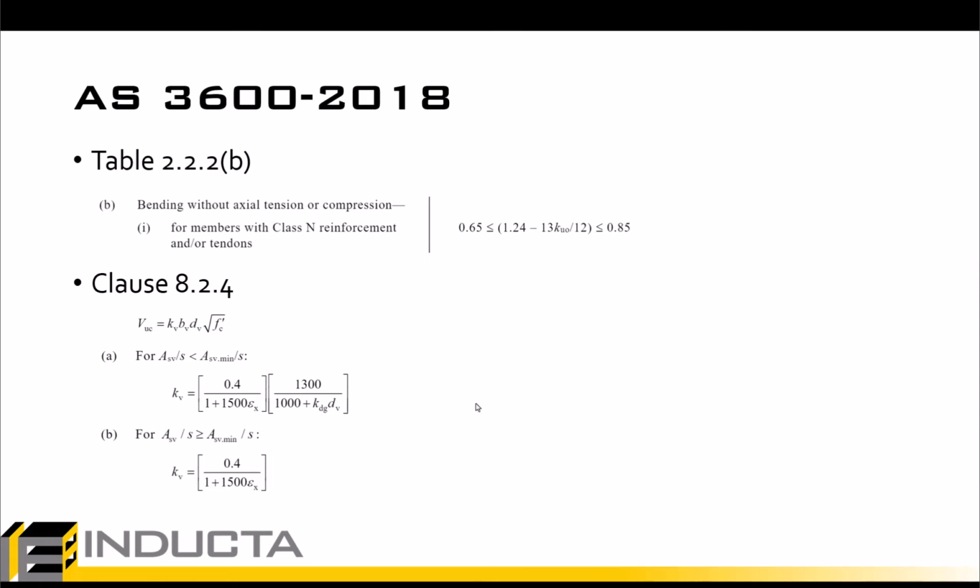Basically, the same reinforcement may provide different capacities for different load combinations, hence we cannot produce a single value for the envelope. We can only record the smallest safety factor and governing load combination, which we do, and this information is available from the results table when envelope is selected. Now, let's move on.